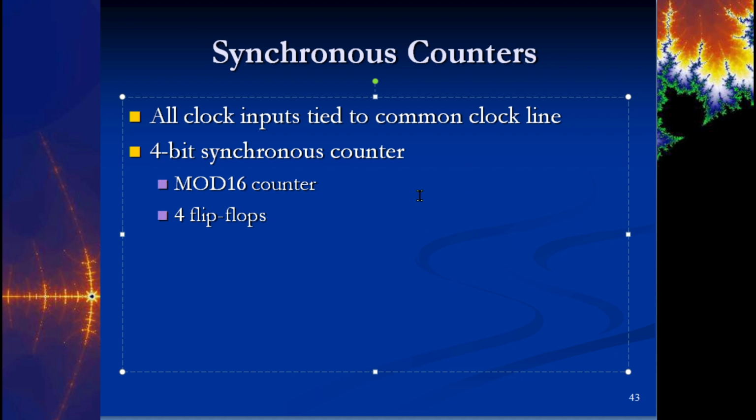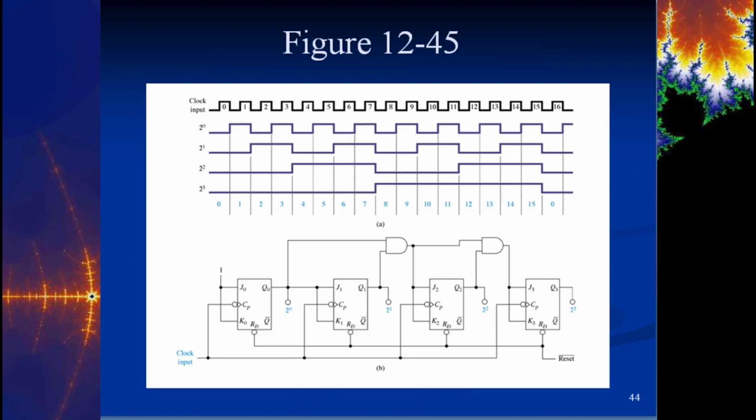Okay. So here is a 4-bit synchronous counter, just a mod 16. So this is the synchronous version of a 7493 that can do mod 4. Okay. So again, we're using JK flip-flops, but notice that we're using some of this external circuitry now. Okay, so it's not as simple as just cascading into the next. All of the clock lines are tied together. Notice that only the first one is in toggle mode. Does everybody see this? JK. Right? So these are both tied high.